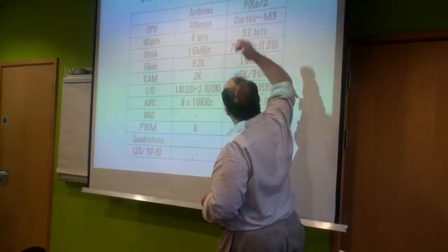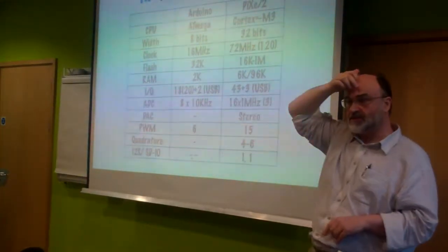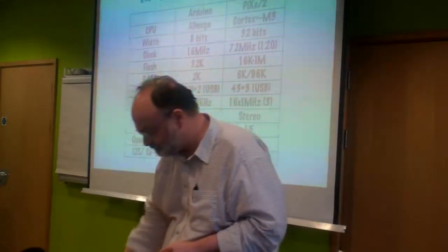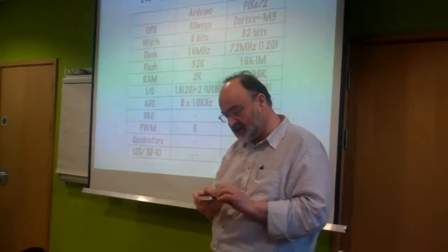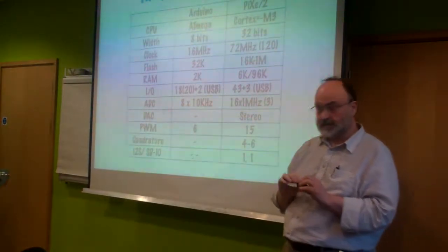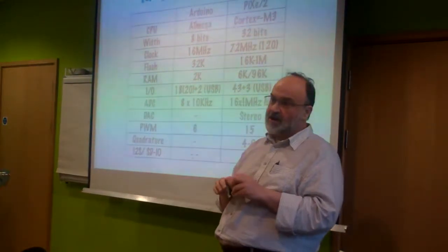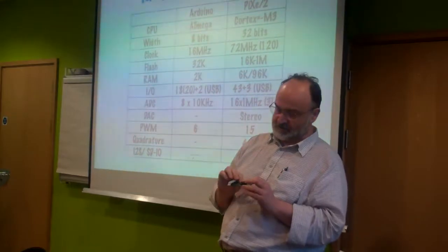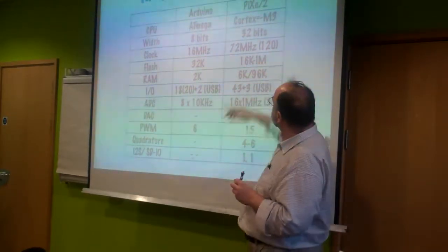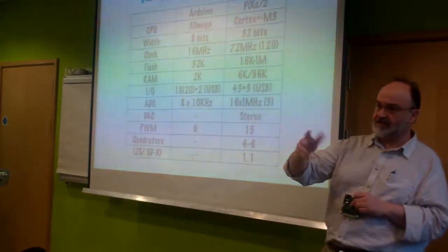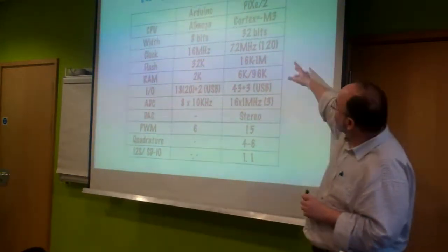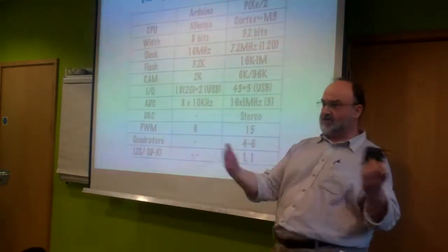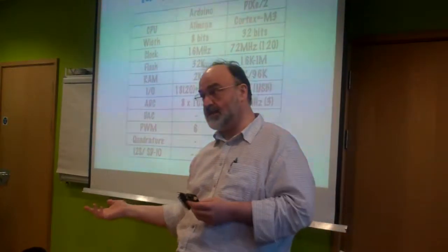Over here, the thing that I'm using is a Cortex M3, which is an ARM-designed processor. The particular flavour comes from ST Micro. I'm using a 64-pin part, which is how I get the extra 20-odd I/O pins. It runs about 72 megahertz, so about 4.5 times faster. It's 32 bits instead of 8 bits, which often doesn't matter because all you're doing is tootling up strings and characters. But in reality, a lot of the time you're using 16-bit numbers, so it does maths quite quick.